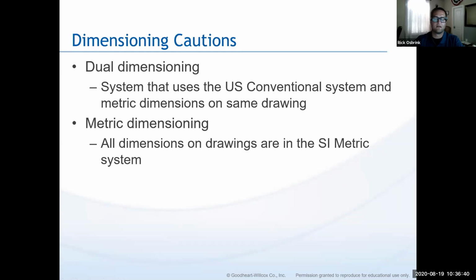You either have maybe the imperial measurement, and then in parentheses you'll have the metric measurement. Sometimes there's just a slash, sometimes there's one on top of the other. So it just depends on how the designer tries to articulate that to you. So you have to be really careful with that to make sure that you're using the right number, right? That we're either using metric or standard, and we know that,